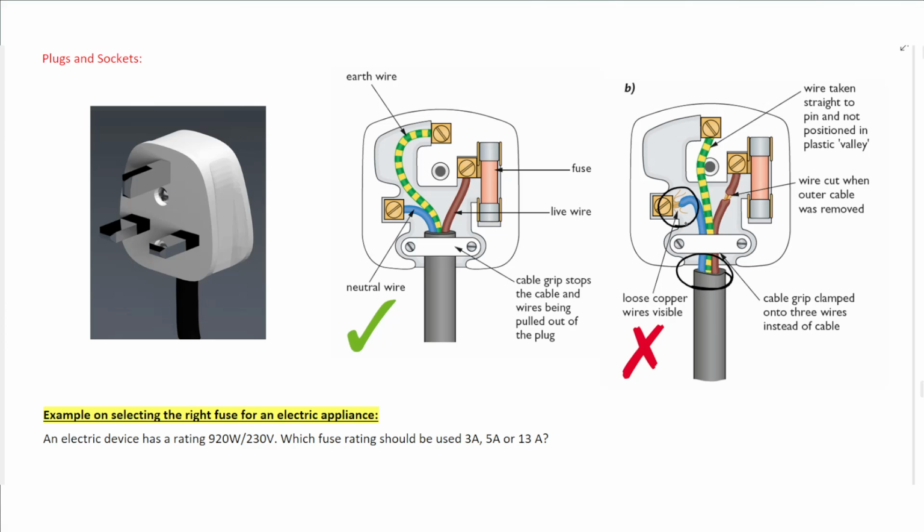So if you want 4 amperes and you are left with choices, a fuse that can take 3, 5, or 13 amperes: you cannot choose 3 amperes since the current of 4 amperes will always blow the fuse. And you cannot use the 13 amperes since it is much greater than the 4 amperes. So the current can reach 13 and this will damage the object. But it does not necessarily have to reach 13.